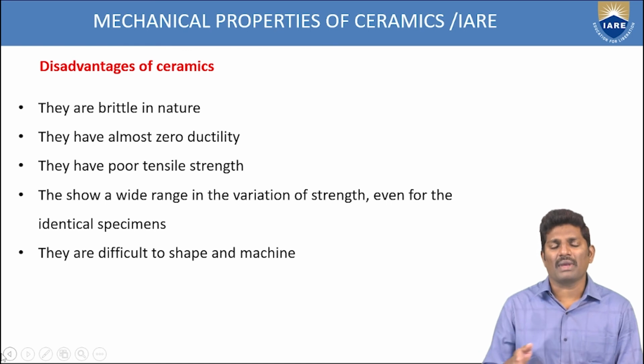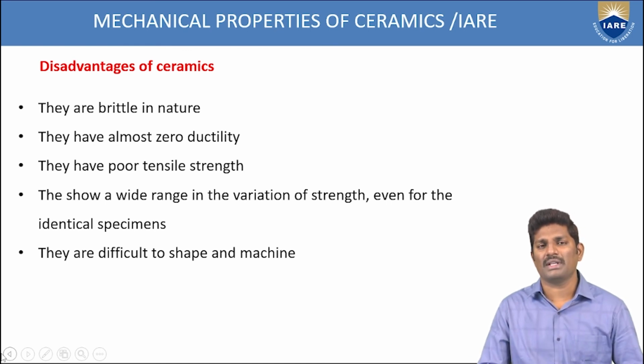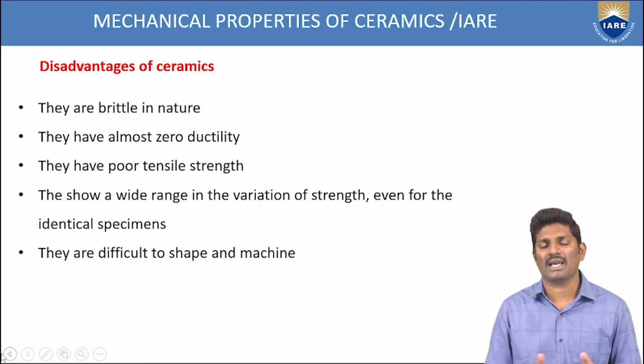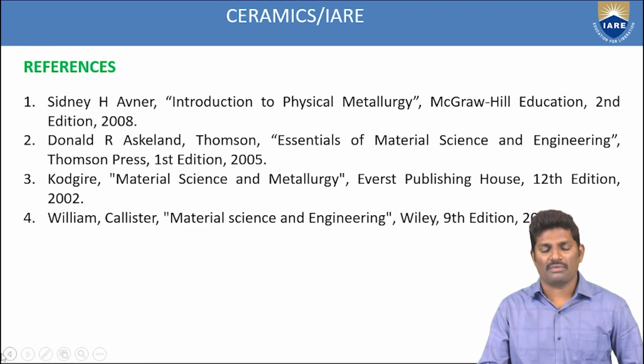And coming to the mechanical properties, the brittleness is very high when you apply different types of loads on the body. Since it is very brittle in nature, you have very limited applications using ceramics. Once you prepare a ceramic into one single shape, you cannot alter the shape. That's why the machining and shaping of ceramics is very difficult when you compare with metallic and non-metallic elements.